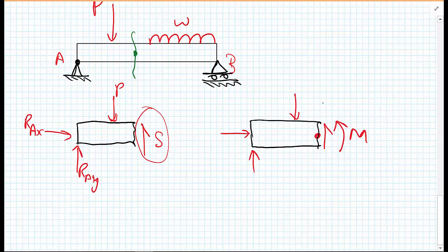And also, we don't need to consider the shear force in that moment, because the shear force will be going straight through the point where we're taking moments and therefore has no lever arm. But we'll come on to these examples as we go along.